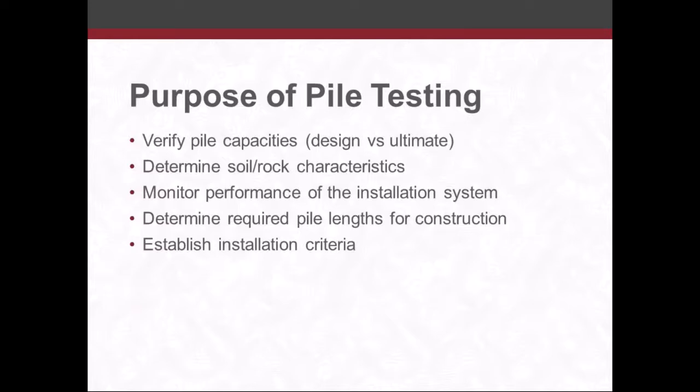So the purpose of the pile testing is going to be to verify the pile capacities, and we always want to test to the ultimate capacity, which in allowable stress design is going to be the design capacity times a safety factor. For LRFD projects, the term nominal resistance or nominal capacity will typically be used, but we're always going to be testing to the ultimate or the nominal.